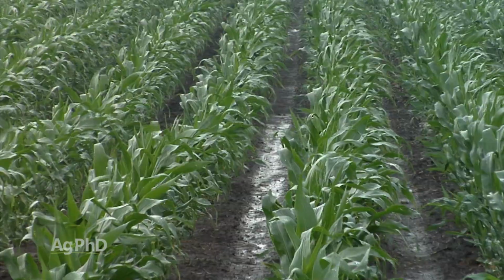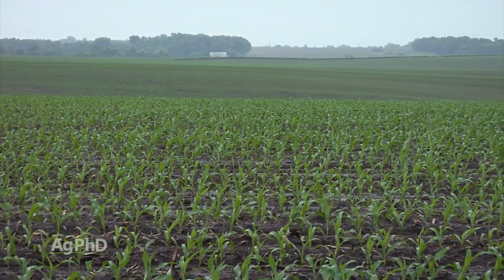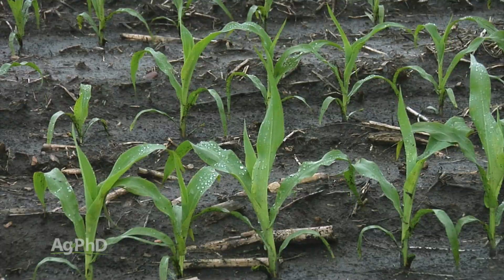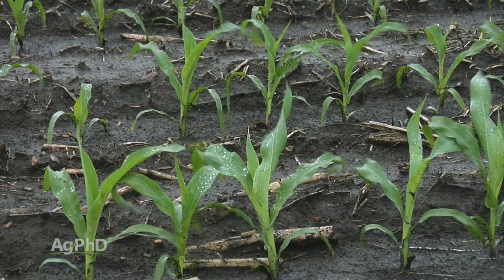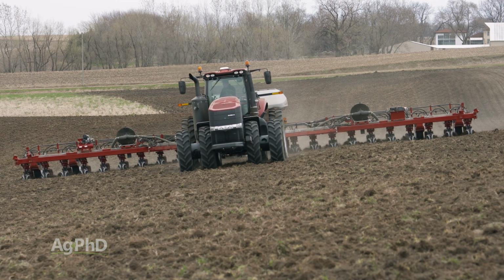But if we put the rows crossways on the hill, now all of a sudden rain is going to hit a row and stop. Then it's going to get to go a few more inches and hit another row and stop and so forth. And it takes a lot of that momentum out and it greatly reduces erosion potential. So when you farm across the hill, that's called farming on the contour.